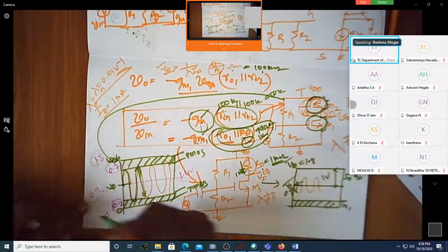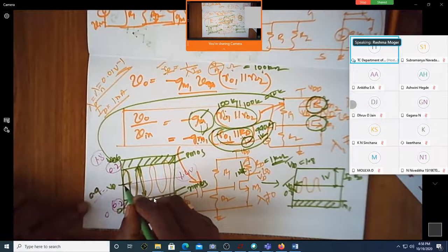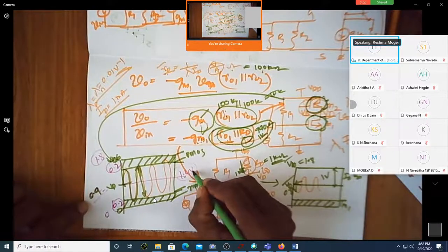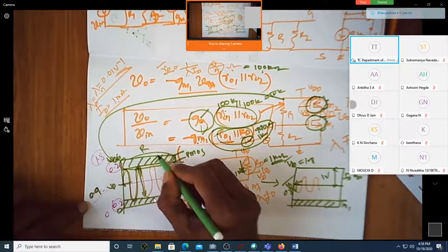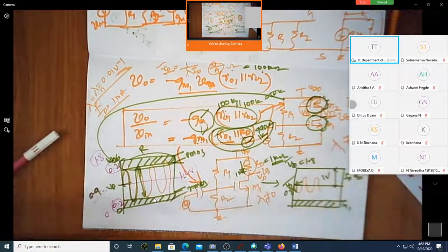Yes, sir. See now, if I can make this swing at around 0.8 volt, how much is the available swing? It is 1.4. This transistor is offering very high resistance and it requires very small voltage to offer that resistance. Am I correct? Yes, sir.